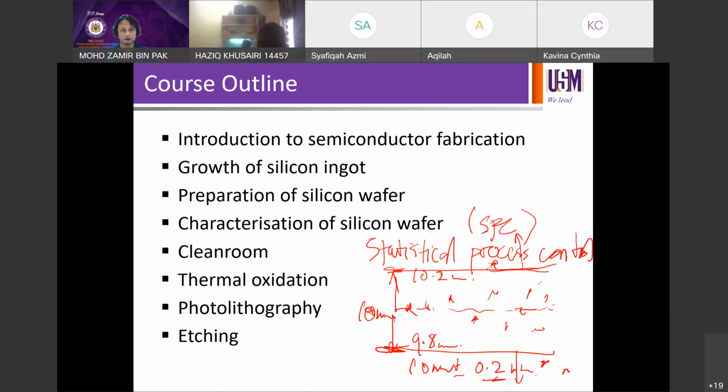And then lithography, the printing of features by light. And then the etching process, the process that follows lithography. They normally run in pairs. You have to have your printing, and then you have to have your removal. Etching is removal, okay?